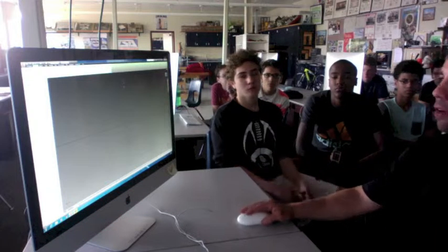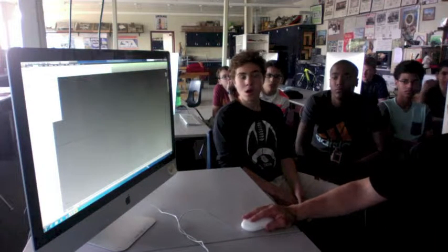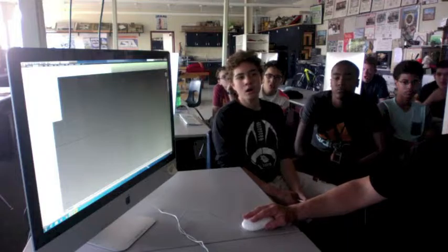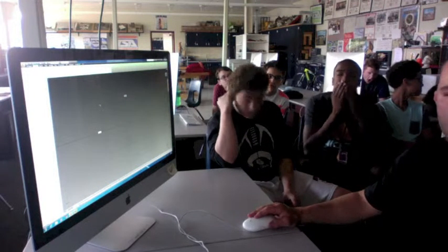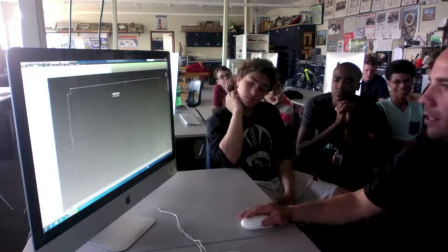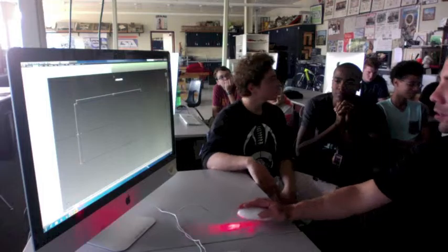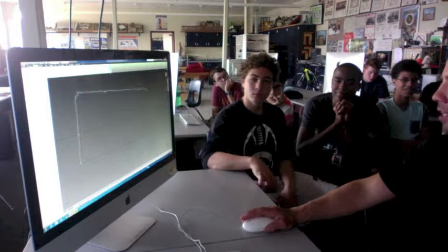And I'm in a 2D environment now, and I'm going to sketch my first part, which is part 1. And I'm going to do just a 2x1 rectangle. So I go to my rectangle command, and I'm going to go 2-point center. So I pick the center, and I drag out. And as it increments here, I'm going to put 2, tab, 1 for the height. And it's completely, fully constrained. I'm going to hit finish sketch.